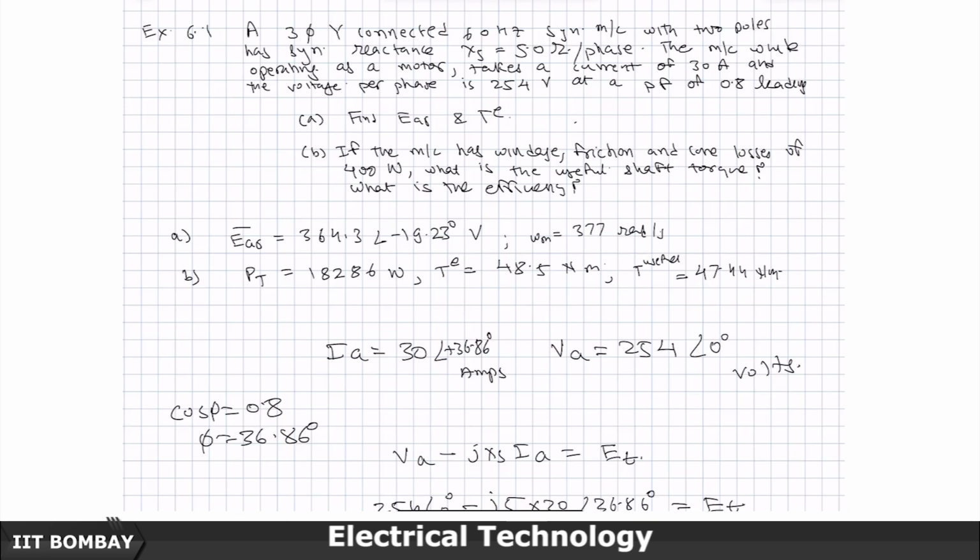a core loss? No, the rotor winding of the synchronous machine does not have a core loss. Why? Because the 3-phase rotating field created from stator currents is also rotating at synchronous speed. The rotor is also rotating at synchronous speed. So, there is no relative change of flux seen there. Therefore, no EMF will be induced in the rotor, and no currents will flow.